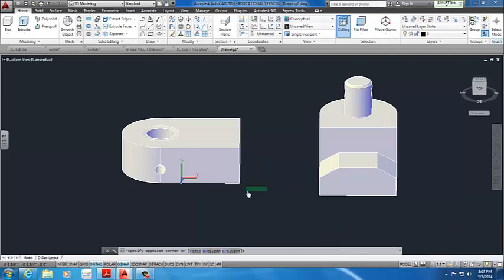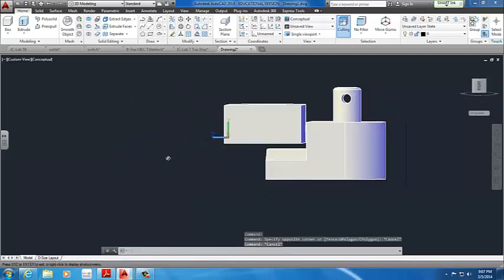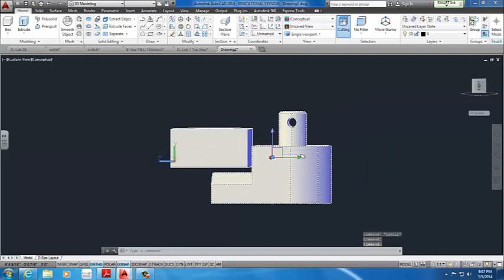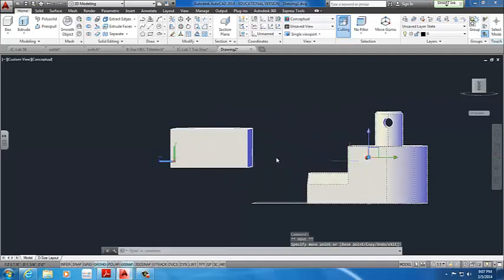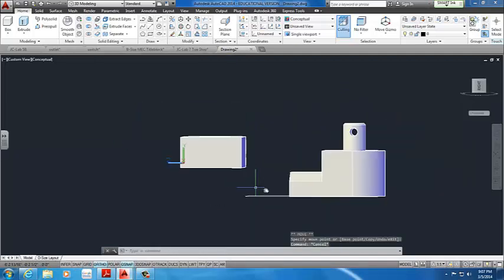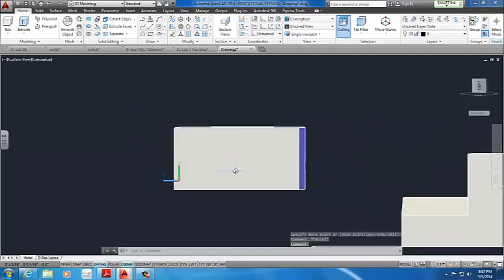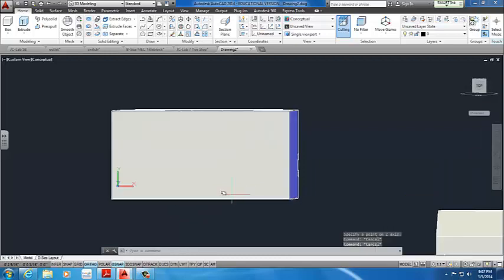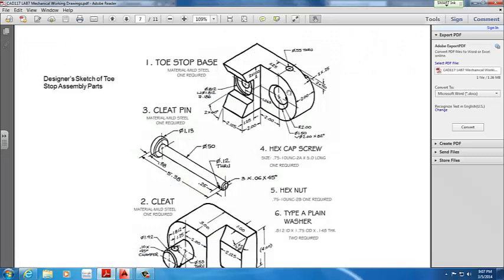Now what we want to do is cut those 2 slots on the side. So I'm going to move this object over. It's in my way. Selecting it and just moving it. It has the original sketch, but that's alright. We want to draw on this face. So we have to make sure we rotate the Z-axis to face us. There we go. And we're going to create those 2 rectangles that are going to be cut through, which is